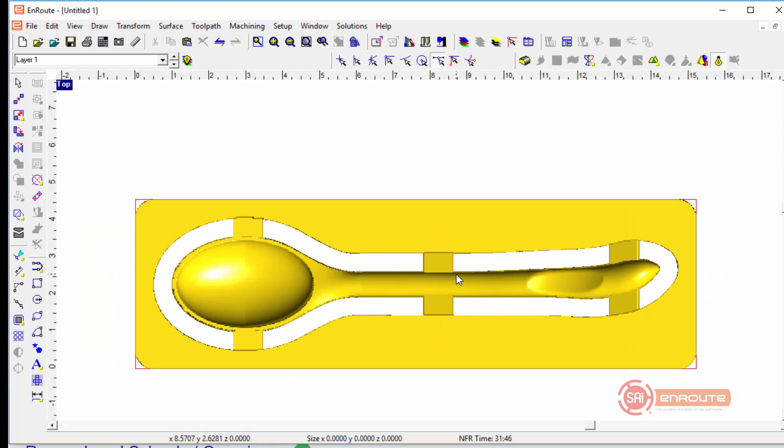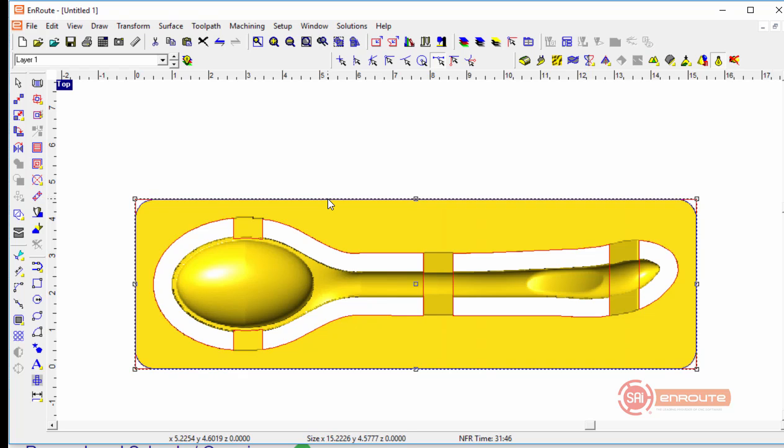So that's something we might consider right at the end, just putting a couple of circles right 1/2 inch or 1/4 inch in from the edge, right in the middle, and then we'll use that as a registration when we flip the part. All right, so let's go ahead and finish the toolpathing on this side, and then we'll create side 2.